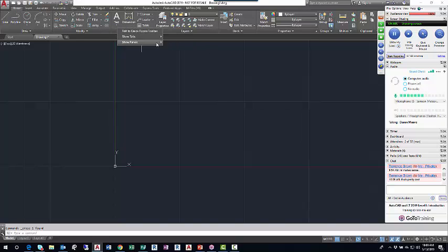One of my favorite tools, not only a command, but this window right here on the layer panel, this shows me what is the active layer in my drawing. In a brand new drawing, you only got one layer, it's layer 0. But if I right click over that window, I can add it to the Quick Access Toolbar. So it just showed up here. And that's kind of redundant.